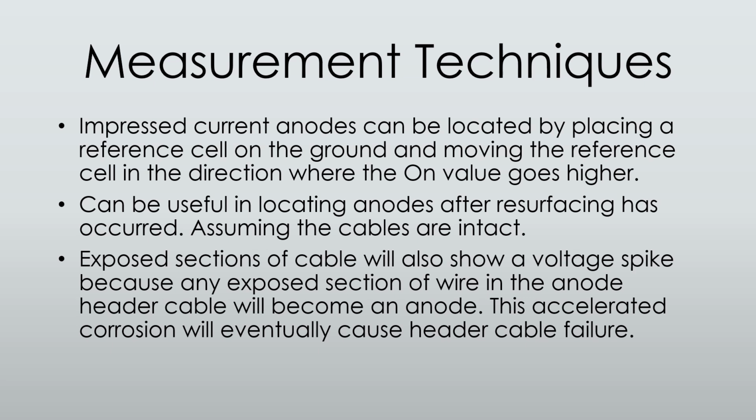Sometimes you get resurfacing companies that specialize in gas stations. They run into these wires and they kind of know how to handle them. But then you come back in 2.5 years after you surveyed the system and there's a new parking lot and you have no idea where anything's at and you're trying to troubleshoot anodes. You can't see where anything's at. Sometimes this is a good technique to have in your back pocket.